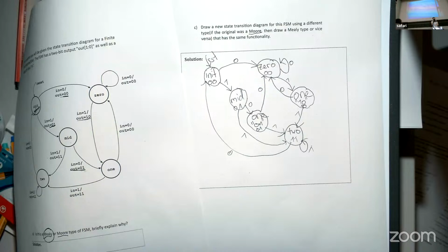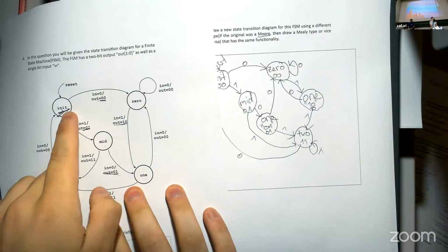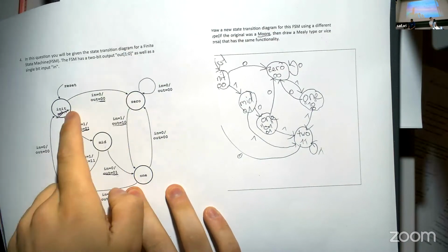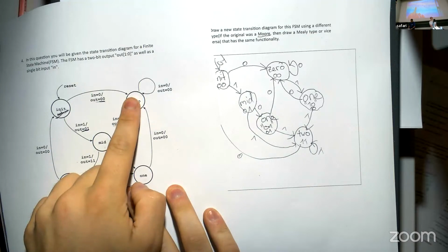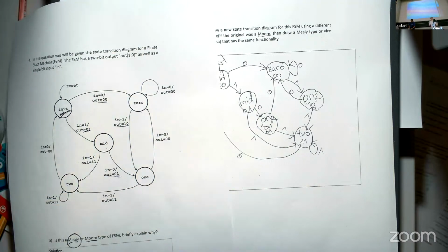The way to interpret these states essentially is to think of the output on the edge of a Mealy machine as equivalent to the output on the state of the Moore machine. So really the output you're getting here is the output that's over here, right? Essentially it's the first cycle of your execution that's undefined. But in practice, it's not an issue, I guess.